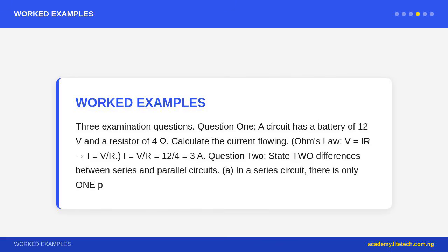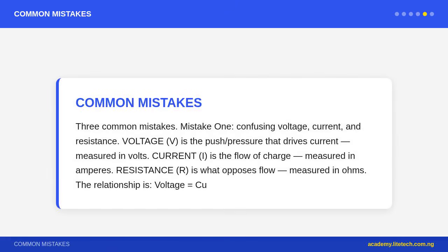Question 3. Explain why household wiring in Nigeria uses parallel circuits rather than series circuits. In a parallel circuit, each appliance is connected independently to the supply. This means, A. Each appliance receives the same mains voltage, 220 V. All appliances operate at their rated voltage. B. If one appliance fails or is switched off, the others continue to work independently. You don't want your fan to stop because your television broke. C. Each appliance has its own branch switch for independent control.